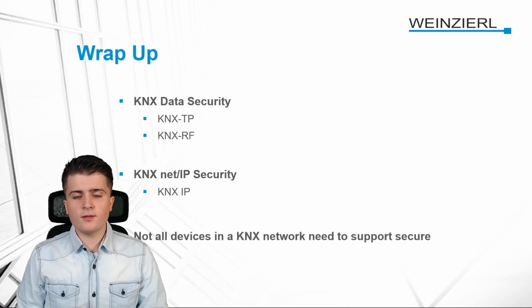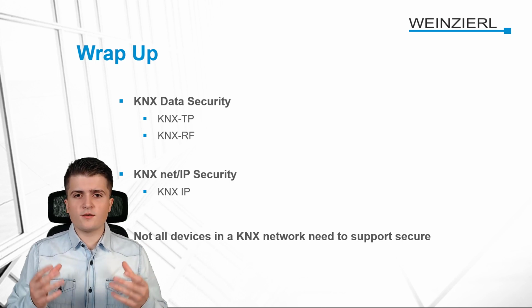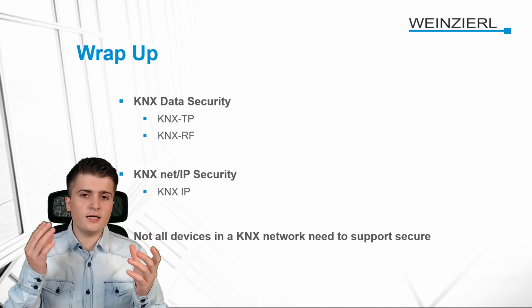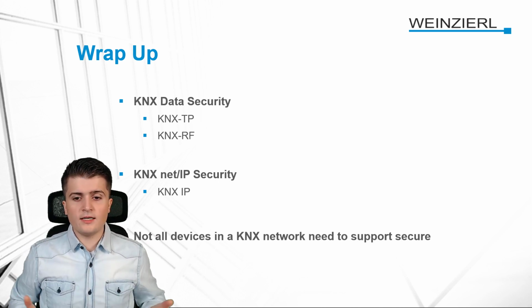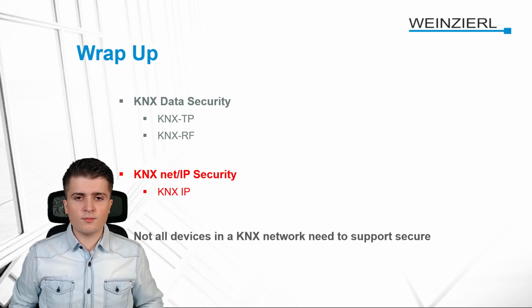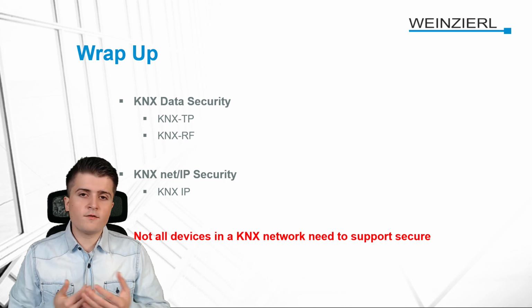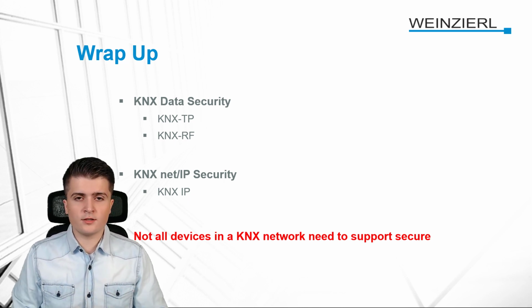So let us do a wrap up of what we learned so far. First of all, we saw that KNX Security consists of two components, KNX Data Security and KNX NetIP Security. KNX Data Security is used by KNX Twisted Pair and KNX Radio Frequency, while KNX NetIP Security is only used by KNX IP. However, we might have two components of KNX Security, but both of them use the same encryption standard, AES. And it is important to know that not all devices in a KNX network need to support Secure in order to use Secure, for example if you only want to use Secure partially in your network.